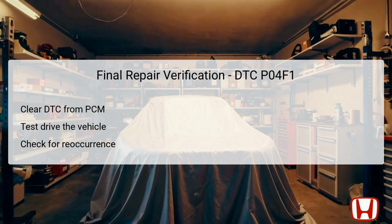After completing repairs for DTC P04F1, the final step is verification. Start by clearing the DTC from the Powertrain Control Module, PCM, removing any temporary fault codes that were stored during the diagnosis. Next, conduct a test drive under varying conditions to observe whether the vehicle's performance remains normal, particularly concerning emissions control. Pay attention to whether the dash warning light reappears during or after the drive.